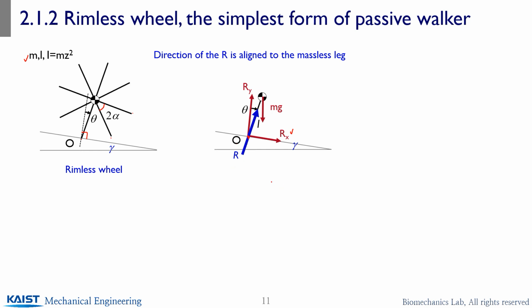Okay, so the basic equations of motion for this configuration are going to be the torques applied with respect to the point O, which is I_O theta double dot. And the torque applied here is only by the gravity, so the L vector from O to the center of mass, cross product mg, is going to generate the torque that equals I theta double dot.